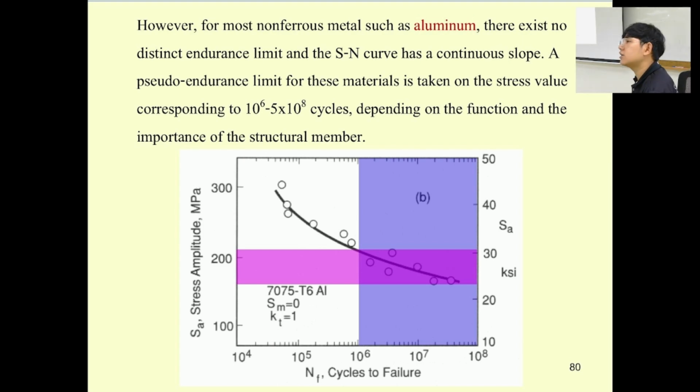They can test it for fatigue, but they don't have the endurance limit. When they don't have the endurance limit, they need to always check it for the airplane wing, for example, right? And then they're going to set a really high factor of safety of the failure cycle at the minimum over here.